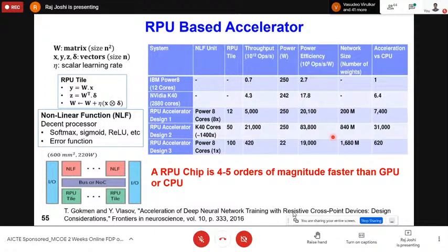That conduction changes because of the material property, because of the application of that voltage, and then you can create a memory as well as computation, because once you turn on that word line, you can read the current from it, and you can sum the current using those physics laws that I mentioned, and then you can get results. So you can solve DNN, CNN kind of networks using these techniques.